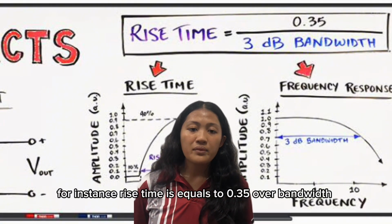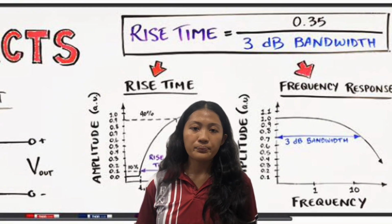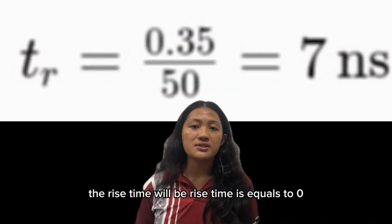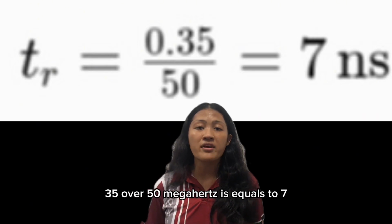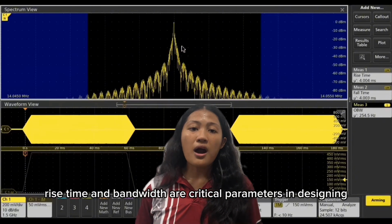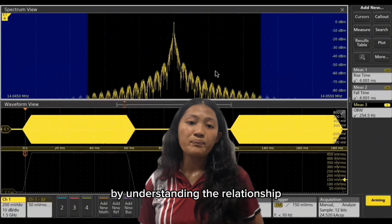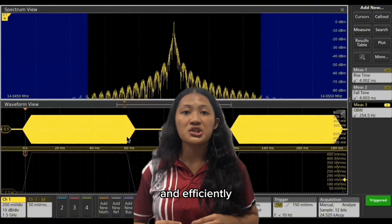By rearranging the formula, we can also calculate the rise time if the bandwidth is known. For instance, rise time equals 0.35 over bandwidth. If a circuit has a bandwidth of 50 megahertz, the rise time will be 0.35 over 50 megahertz, which is 7 nanoseconds. All in all, rise time and bandwidth are critical parameters in designing and analyzing communication systems. By understanding the relationship, engineers can ensure signals are transmitted accurately and efficiently.